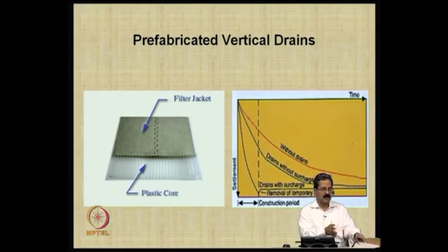But the problem is that over a period of time the clay and sand get mixed up, and there will be a problem between the soil and sand. There will be some places where the permeability is again poor; the sand column will not be a complete sand drain, and some area gets smudged, what we call the smear zone, and the permeability of the smear zone is very important.